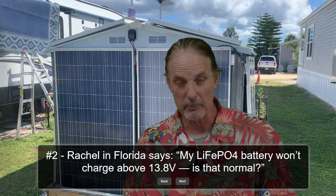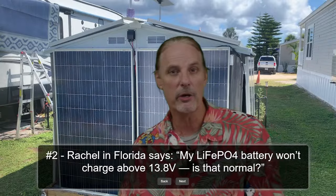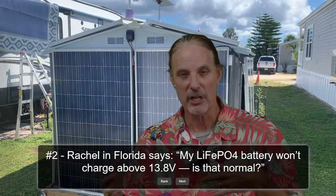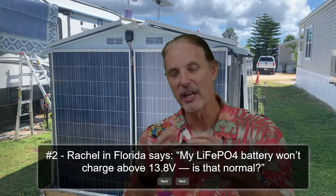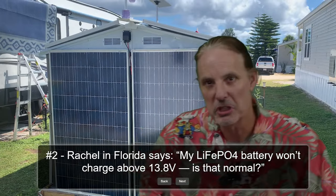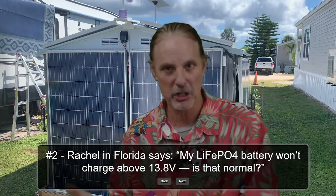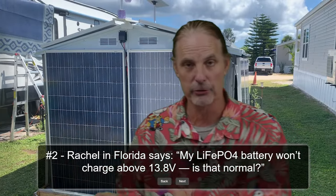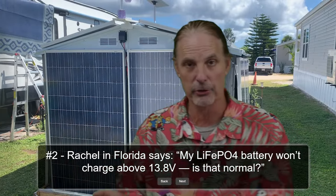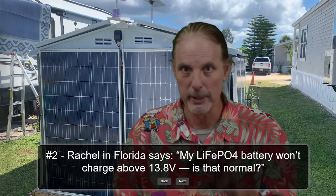And especially when it comes to balancing, there are other settings of minimums and maximums and where is best to do that based on the LifePower4 batteries and how they would best be suited to take and transfer that power. But in this particular case, we're talking about a JK BMS, which has an active balancer, or the LifePower4 has a passive balancer, and pretty much most batteries fall into one of three categories.